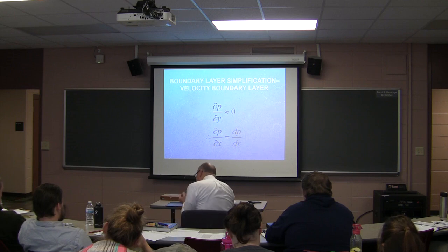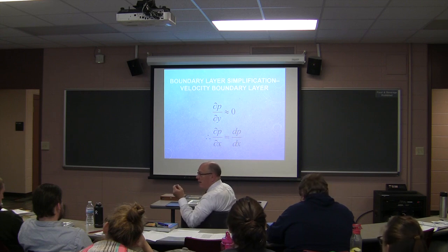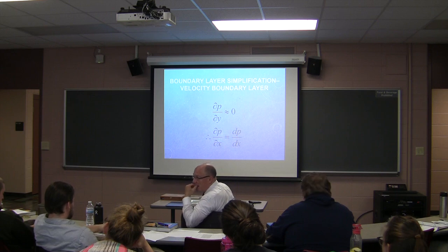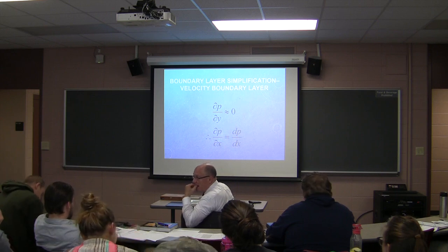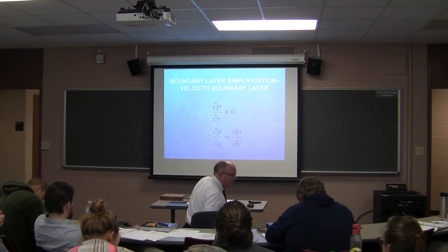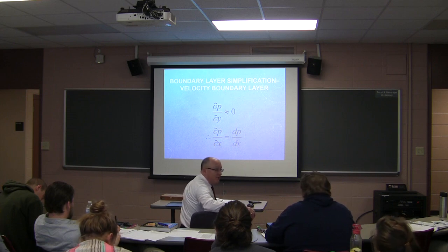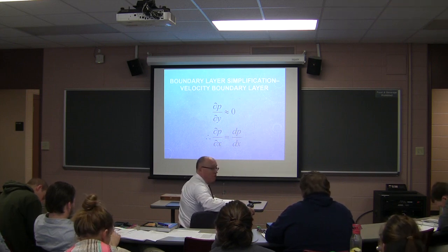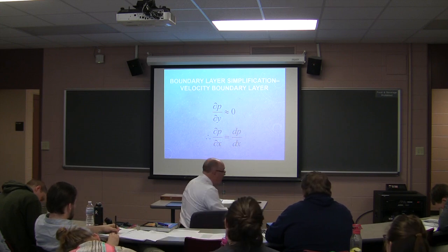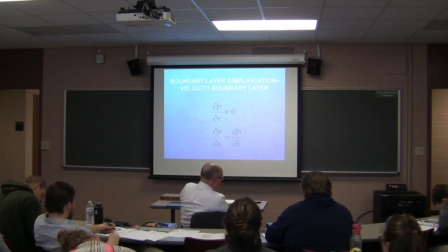So what does that physically mean to us? It physically means that the frictional pressure drop is what? 0 in the x direction? What? 0 in the x direction? No, not 0 in the x direction. Constant. Constant. Which goes along with what you see with all the stuff in fluid mechanics. Okay? So, in other words, the frictional forces are constant, given a certain geometry.